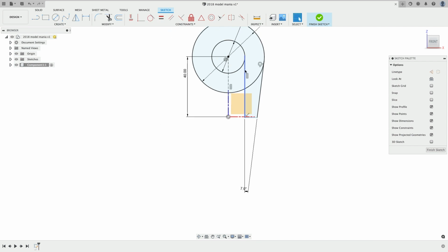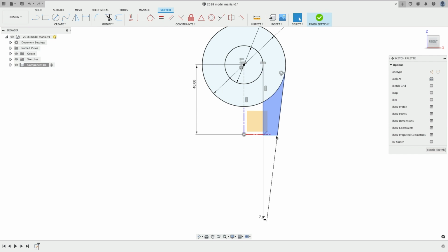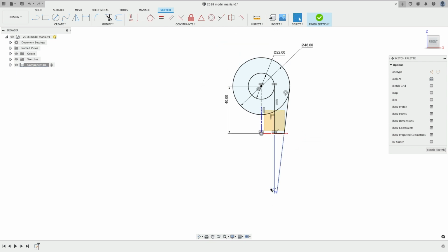Great. Now what's missing on this vertical line here? It can go anywhere in space, it looks like. So if I want to actually snap to a quadrant or snap aligned with the origin, let's do that. So I'll select maybe the origin and right click and say that that's horizontal. These 2 points line up horizontally. Now it's mostly defined except for the length of that line or just how low this sits. Same kind of thing. I can align it with the origin. Right click, choose the points, make them horizontal, and those line up. That's a great way to do it.